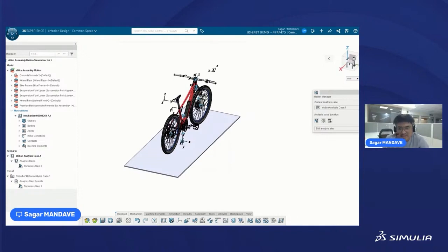If you have an assembly created within the 3D experience applications such as XDesign, XMotion will work best. There will be proper collaboration when you transfer your assembly from XDesign to XMotion: you will get all the products as CAD parts, their material and all the mates within them.